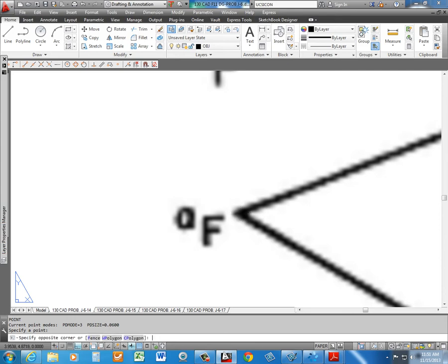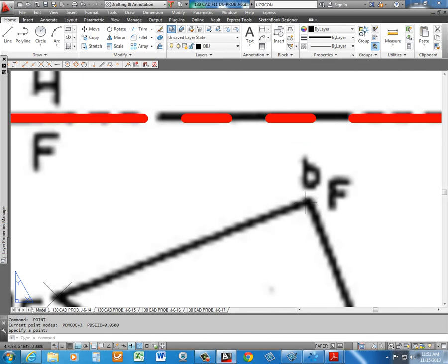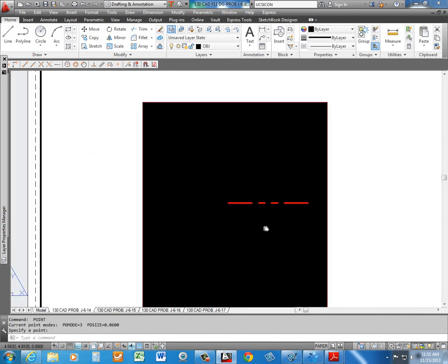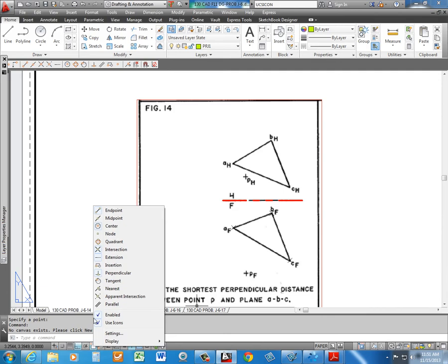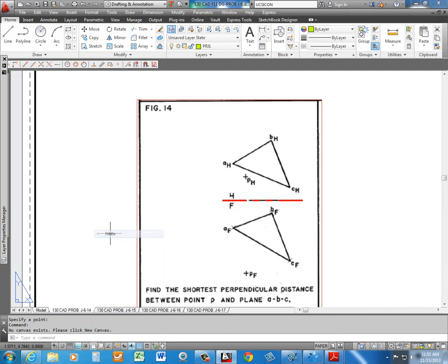Then we will create projection lines, and we will adjust our lines, our shape in the top view, and possibly even end up moving our point just a little bit. Alright, now projection, and we'll need to turn on our O-snap and turn on our node O-snap. And project orthographically to point C. And just do it by eye. That will work very well. It looks like it's going to match it pretty close.